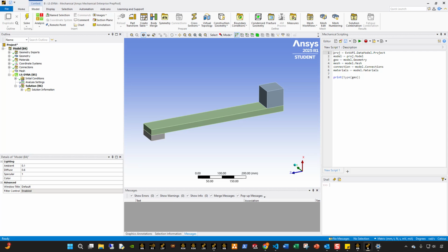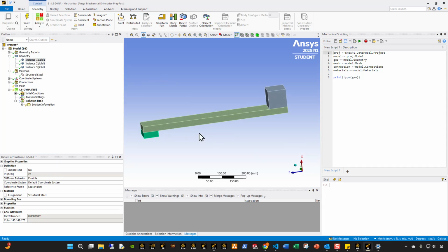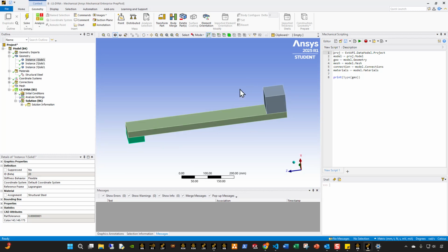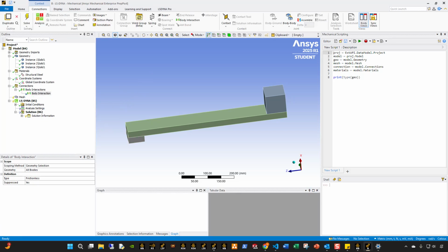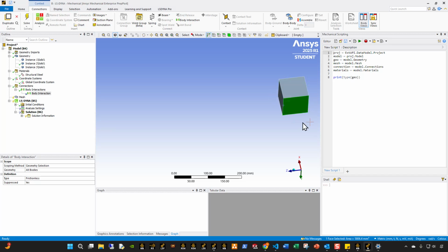Okay, so let's do this. Like I mentioned in the previous video, there is no point in using any kind of insert command or material type of deal, because none of this would register with a thermal problem inside Workbench on the Dyna. It's just not set up yet. So just as I did with the previous video, let's go ahead and get started setting up a few sets. These sets are basically the things that we're going to call with our command snippets or with our keywords later.